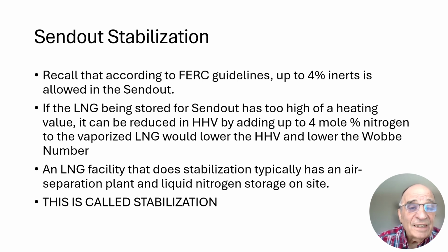Well, so far I've mentioned nitrogen as being a negative when it came to LNG, but sometimes we actually intentionally inject nitrogen into our send out. Let's say we have a tank that has a high BTU content and a high Wobbe index content in the LNG storage, and we want to decrease the higher heating value, and we want to decrease that Wobbe number to make the gas interchangeable.